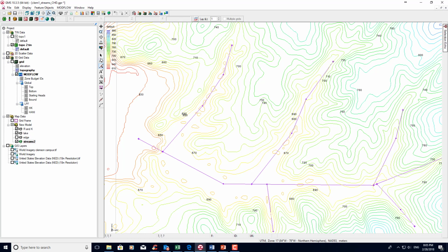And so I put these in, and as a first stab at this, I don't really know how far upstream the headwaters are. So I put the stream here, that'll be the constant head boundaries, up to about the same elevation. So it's about the light green elevation here. And maybe this is a little bit higher. This is a little bit higher yet.